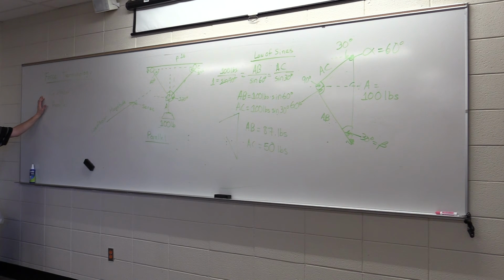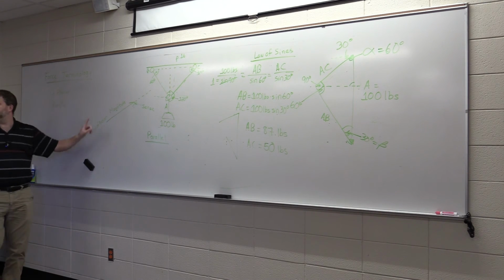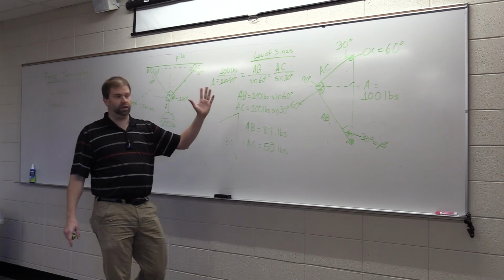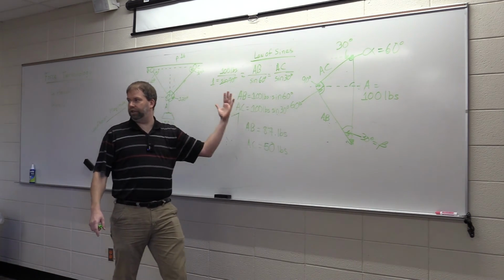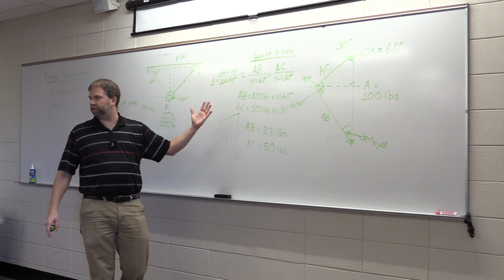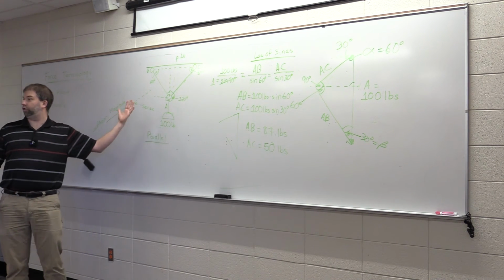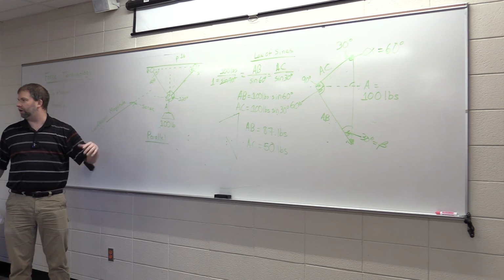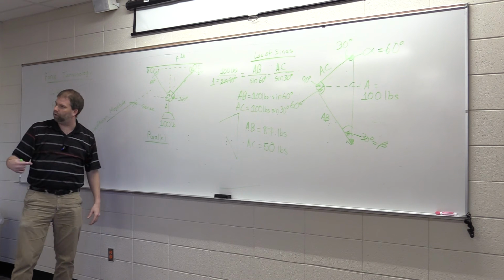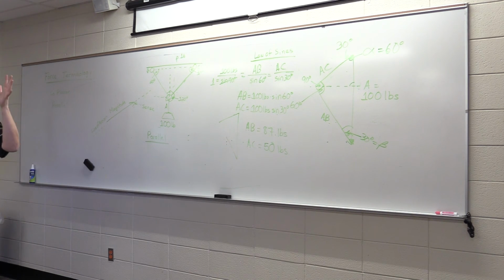So it would be coplanar. What's an example of coplanar? Coplanar would be the forces coming down. Yep, it'd have to be all acting within the plane of that wall. Once it starts acting in a different plane, if we started trying to overturn the wall, no longer coplanar. If we're going through the wall, not coplanar. Everything's got to operate through that same plane. Good question.